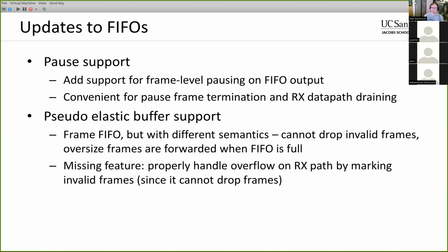frame FIFO would otherwise. The reason this is necessary in Corundum is because I want to have a large shared FIFO module which can handle the various traffic classes as well as multiple ports. And that'll be connected to the ports through asynchronous FIFOs. And having asynchronous FIFOs that can store multiple jumbo frames ends up eating up a lot of block RAM resources somewhat unnecessarily, and also increasing the latency. So if we can replace those with something much smaller that maybe uses distributed RAM, then that would be good.